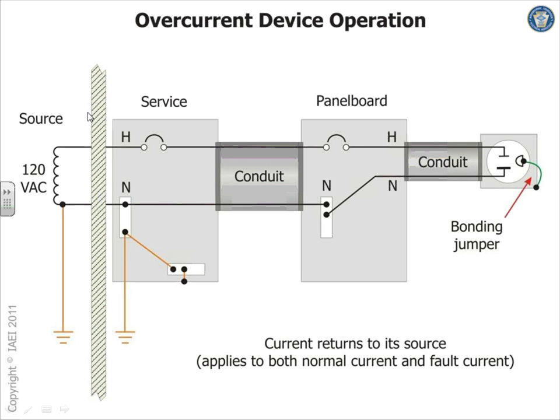Okay, so it talks about, guys, grounding and bonding. Here's a very, very important concept. Here's my service. Right here is bonding the service, grounding the service. You can see it's solidly grounded to Mother Earth. Then you get into the building, and we do the same thing. Inside our building, we bond to our building. Why can't we just depend on this to ground and bond our system?